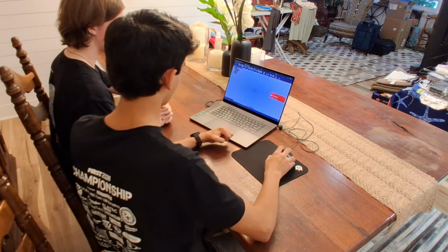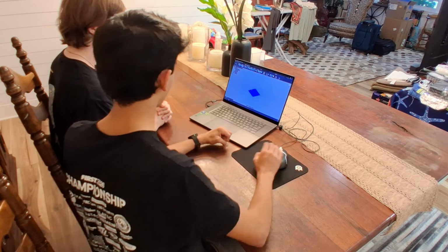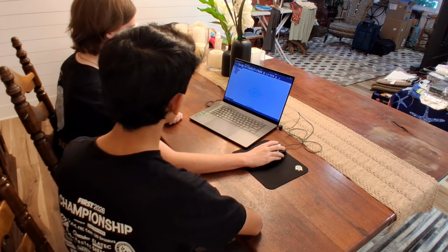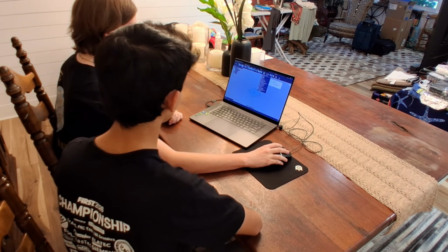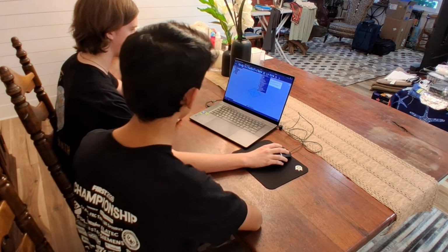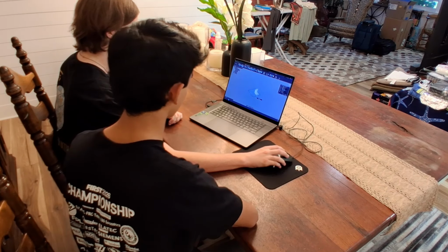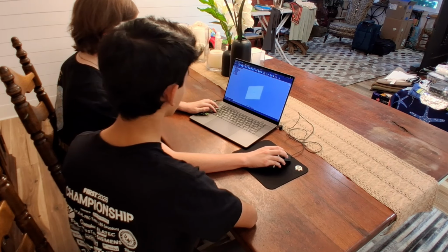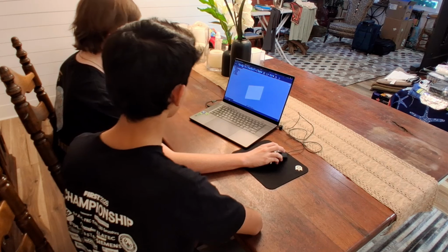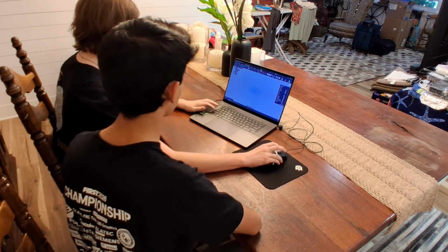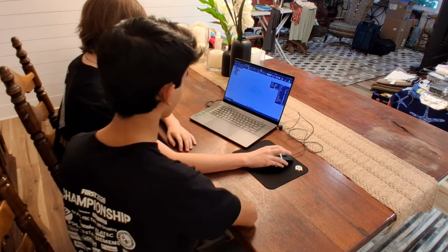Right. Sure. So we're going to go over your side. Alright, take it away. And at an angle, yep. Use your line you made, and bring it up 90. Yeah, there you go. So now you do your sketch on there, remember? Yeah, make sure you project that line, so that way you can see it on your sketch.